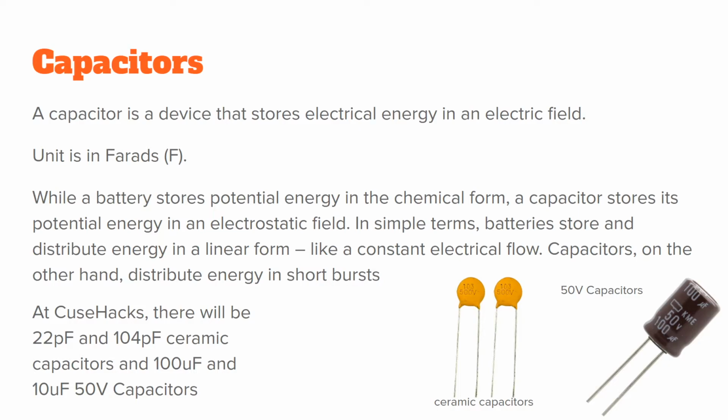Like, if you want to see how a capacitor actually discharges, but one application of it is actually a filter. So, you have an audio sound that maybe has some noise in it. You can actually build a filter with just a resistor and a capacitor. It can be a low-pass filter, which only allows low frequencies, or it can be a high-pass filter that only allows high frequencies. And literally all you need is a capacitor and a resistor, and depending on the orientation, if you flip them, they do different things. So that's one application of it.